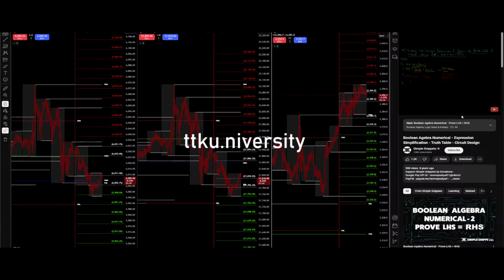Okay, so now we have simplified it further. Now here's the further simplification. AB or, now notice that we have BC 2 times. So we can again apply this law to these two terms and club them to write a single term as follows. This is again due to the idempotent law. So this is our final answer. Now you can further simplify it by taking b common, or you can keep it as it is. So it's your choice.